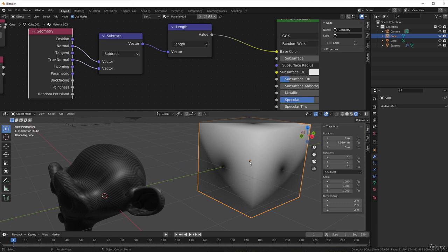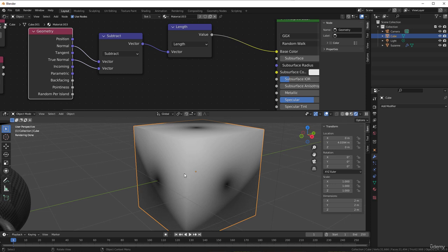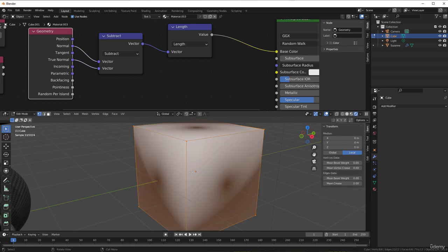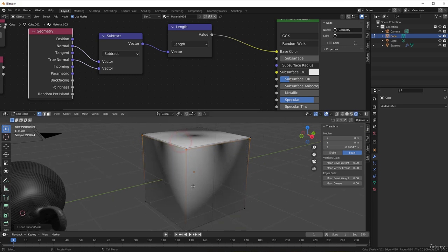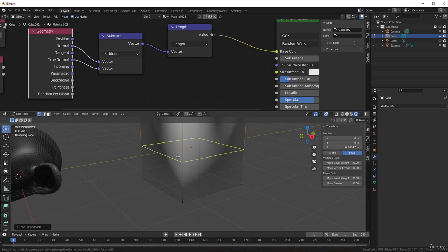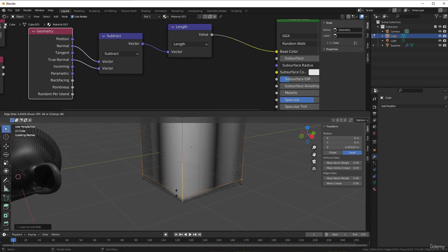So yes, we have shade smooth, which means that we get some difference, but we need to do some changes on the object itself as well. So I will press Tab, and then I will do some loop. So I will press Ctrl R, and just drag that up, and then you can see when I drag it up, the little dot will follow the line here. So I just drag it up to here about, and then I do the same for the bottom one. So Ctrl R again, just drag it down like this, and you can see it follows in a good way.